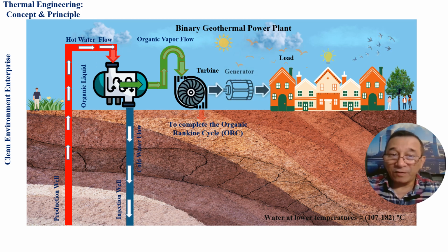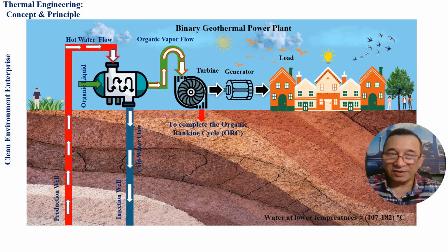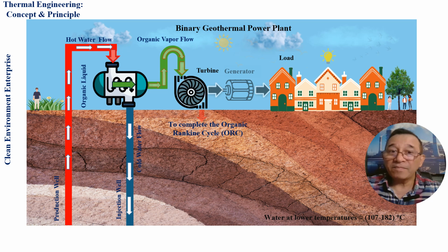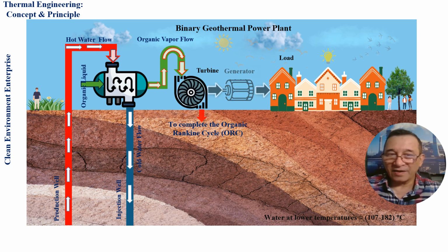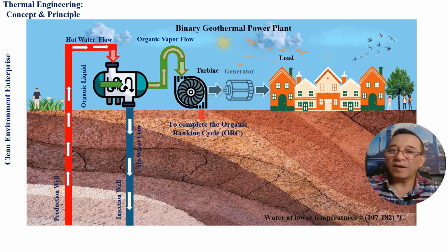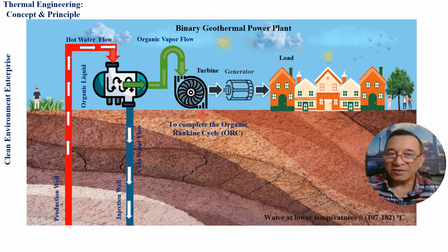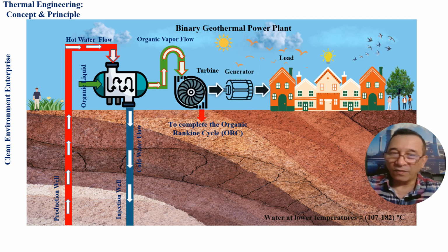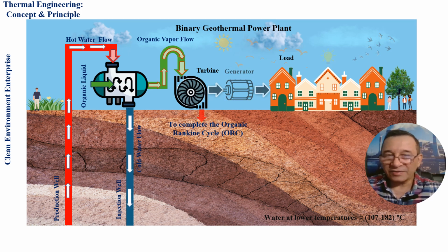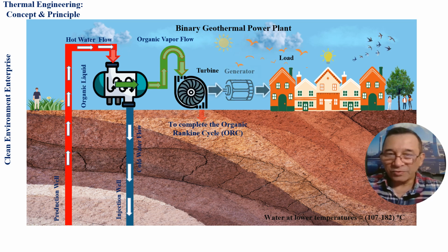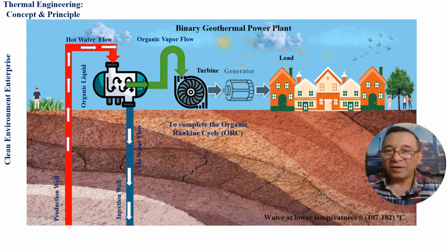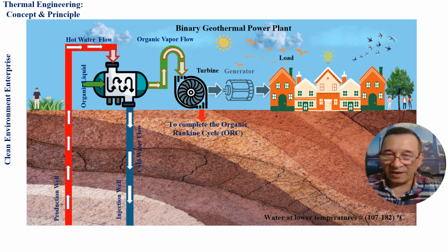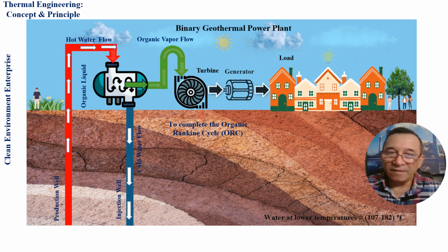The fluid which is circulated in that heat exchanger is vaporized and then passes through a turbine, which is part of a Rankine cycle, to produce electricity with the aid of a generator. In that sense, we produce electricity and supply it to the national network, for example. And the steam is condensed.